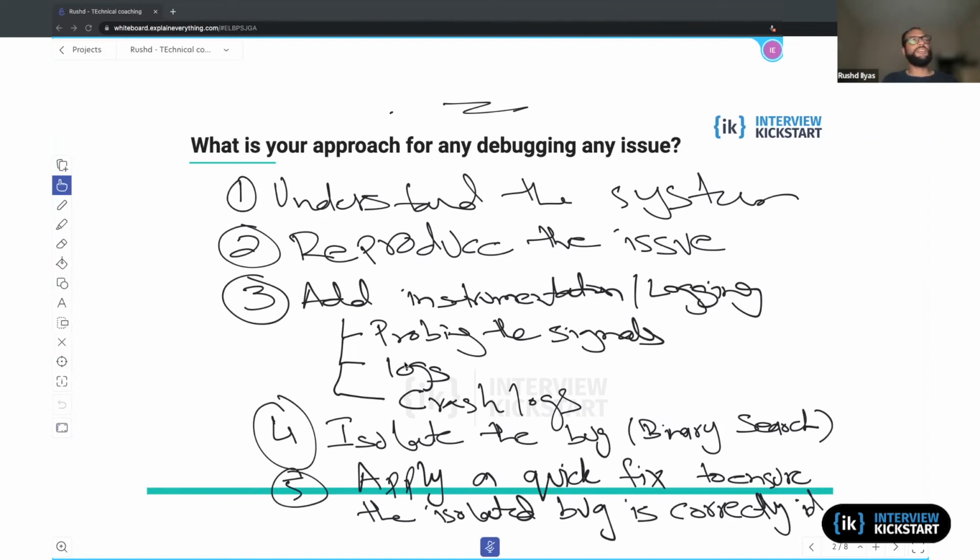The other question is, what do you want to store when a crash happens, before you lose all of that information? Usually it's the stack information: what does the stack look like? It also stores information like the function name. Asserts are really good. They actually store what caused the assert, the line number, and the file name. That has helped me a lot in the past.